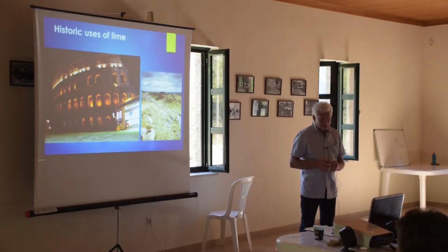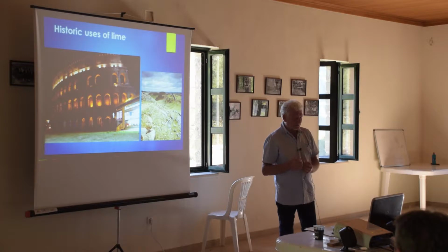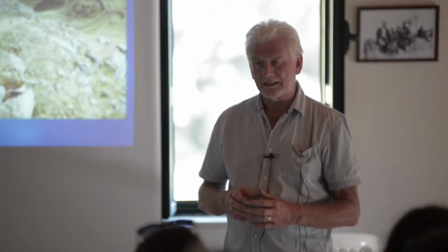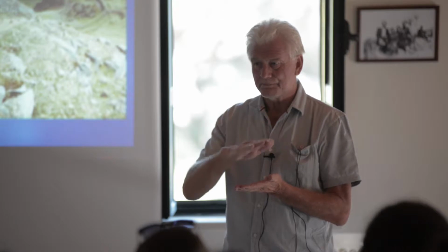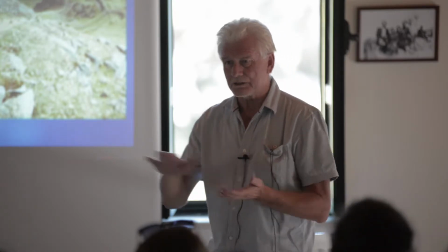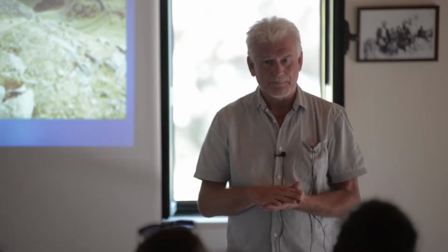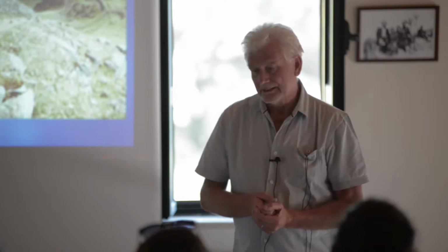The one thing I will say right from the beginning is that when I'm talking about lime and mortars, you must understand that a lime mortar, its purpose is to bind two blocks together, whatever those blocks might be. Mortar is not structural. Okay? The structural element comes, in this case, through the stones.